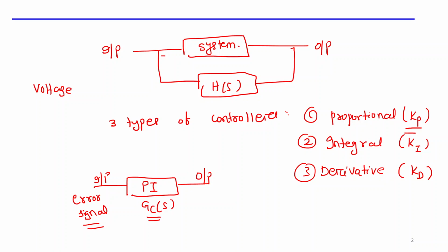So what will happen during the charging time? The charging profile is based on the battery. The battery is charged in CC mode and then in CV mode. CC means constant current mode, and then it goes to constant voltage mode. Initially the current is constant, and after that the voltage is constant. How is your battery going to behave during that charging process? Take any lithium ion battery: it has to go through the constant current and constant voltage profile, because the battery cannot be charged only with constant voltage.